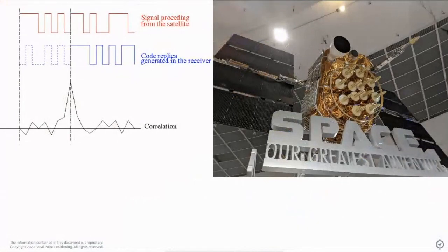It is how you detect the signal from the satellite in order to then use it to calculate where you are. So these satellites are fundamentally very expensive and very clever clocks in space, and they're transmitting the time over and over to us down here on Earth. And in order to pick up the signal from them, we know the code word that these satellites transmit. That code word is inside your GPS receiver. Every satellite has a unique code word, and what your receiver does is it goes searching for the satellite using that code word, using a process called a correlation.